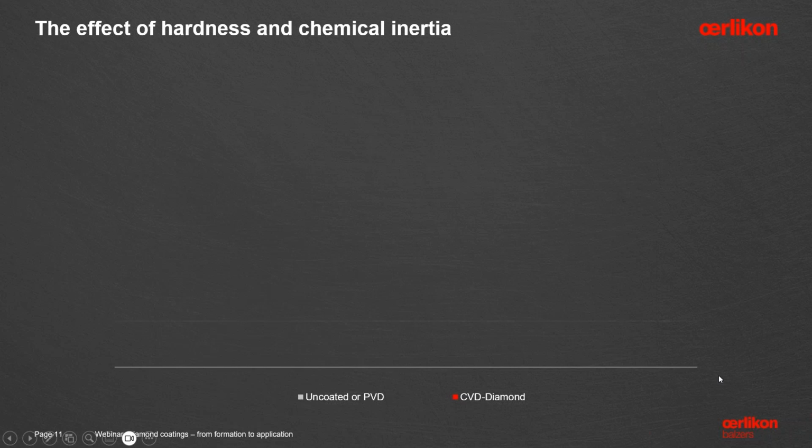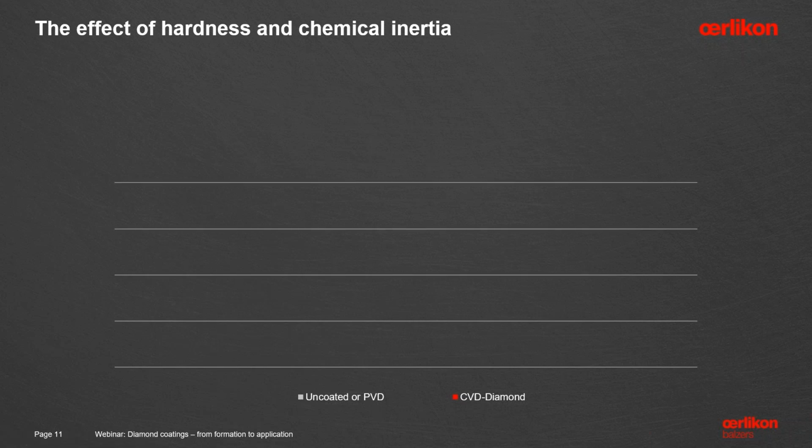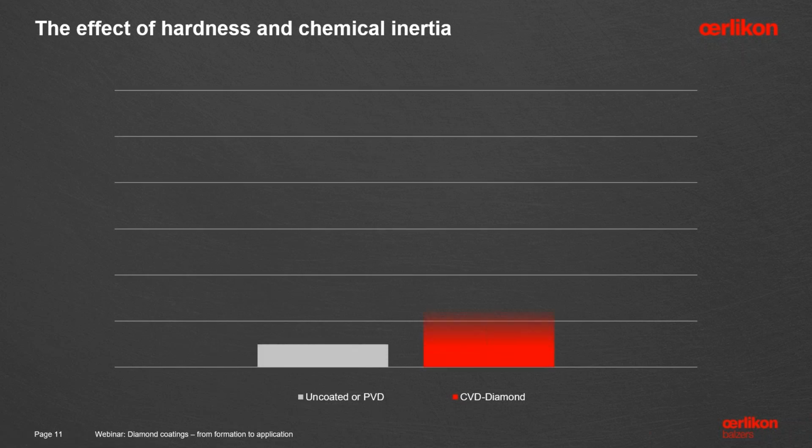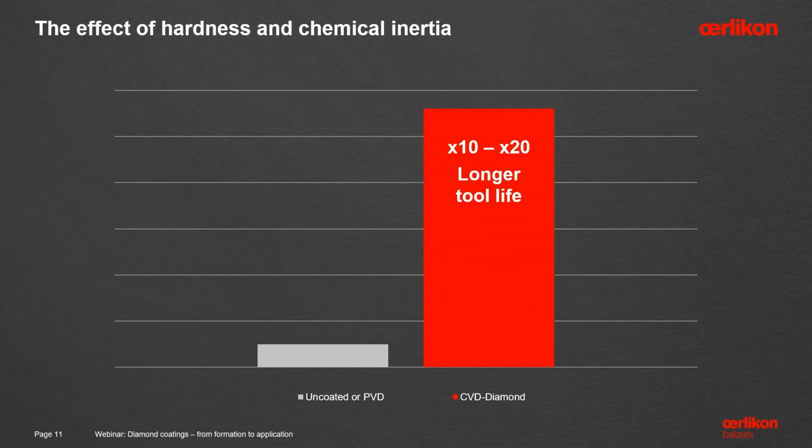And for this introduction, I think here I mentioned before quality and performance. What it is really, the difference is really about the tool life, how long the tool will be able to be used in these materials, and compared to an uncoated carbide tools, or I would say whatever PVD coating would be used, the hardness that we described before of CVD diamond always provide a significant improvement.